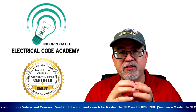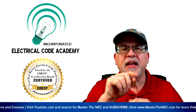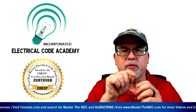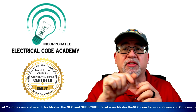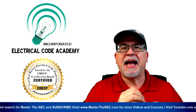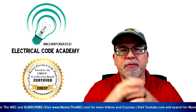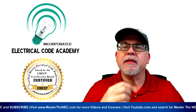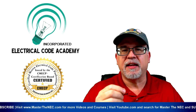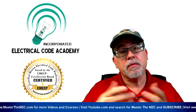You have compressed, which is part of the die process where it compresses it down. You still have some interstices. Now, the interstices are those little grooves or little V between conductors, between the strands, if you will. And then you have what's called compact. Compact is still stranded. It's just compacted so tightly and compressed through a die process that you have no voids in it. So it kind of looks like a solid conductor, but it is still flexible, because it is stranded.